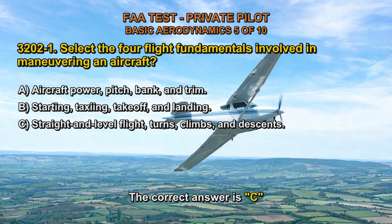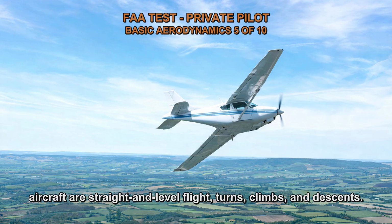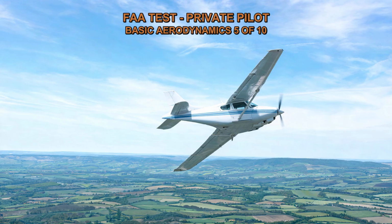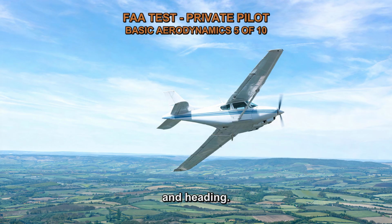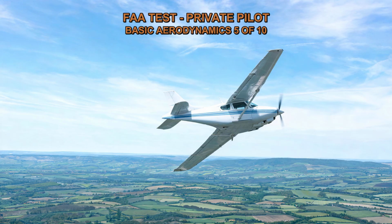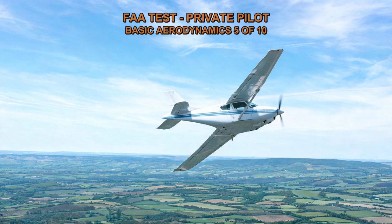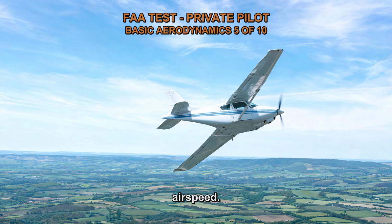The correct answer is C. The 4 flight fundamentals involved in maneuvering an aircraft are straight and level flight, turns, climbs, and descents. Option C correctly identifies these fundamental maneuvers. Straight and level flight refers to maintaining a constant altitude and heading. Turns involve changing the aircraft's direction by banking. Climbs involve increasing the aircraft's altitude while maintaining airspeed. Descents involve decreasing the aircraft's altitude while maintaining airspeed.